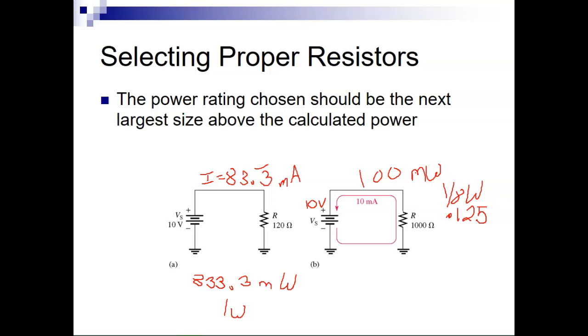Now, do I want to always go grab a 2 watt resistor? Not if I don't need it. The whole reason I grab an eighth of a watt is because I'm trying to put it in a smaller area. Okay, you want things to always be more compact. That's why smartwatches work and things like that, is you have more compact components. It's not going to draw a lot of power, so what's the point of having something massive and something small? It really isn't.